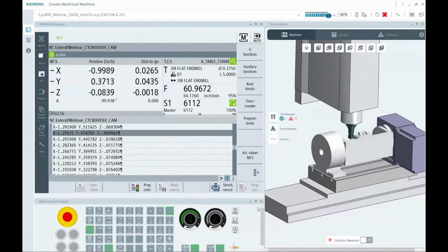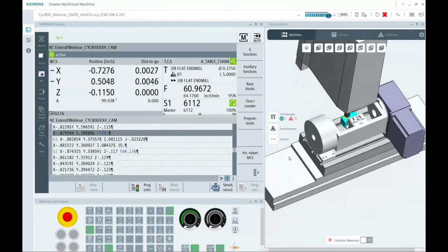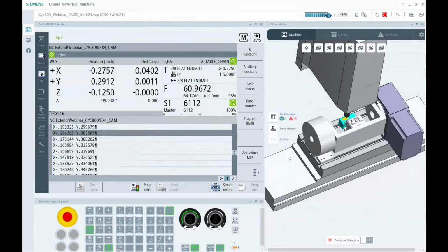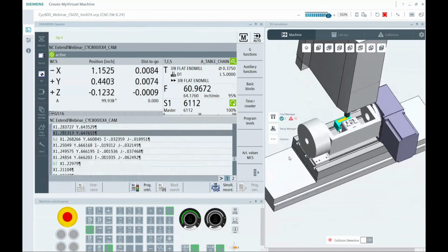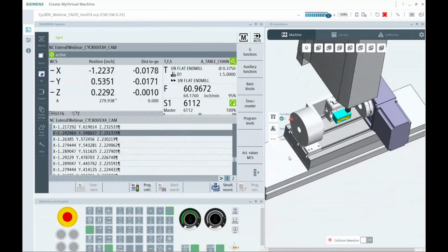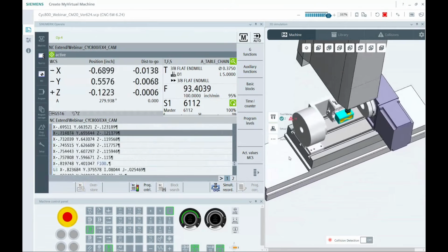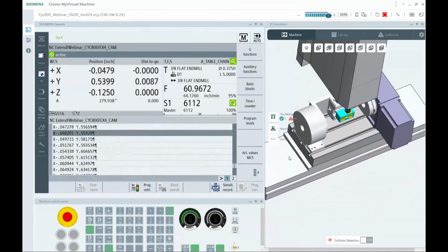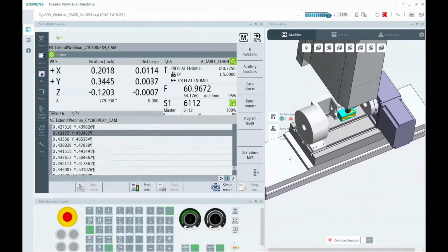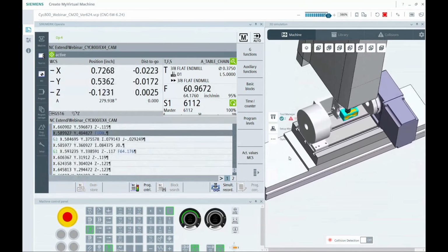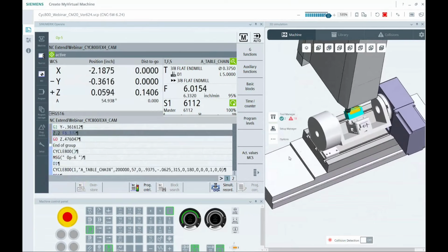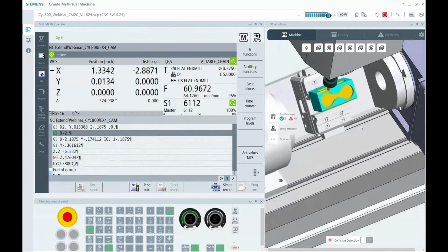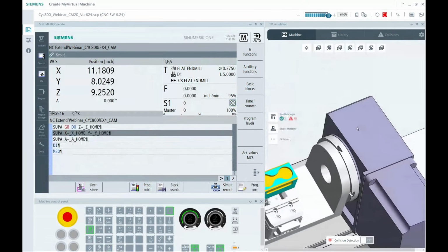There we have our first pocket on that back side, a little dynamic milling to machine that little pocket. And then we're going to wrap it up. I see some CAM systems will use a retract strategy in Cycle 800. Some will still do it with a SUPA on their own. It's not bad either way. Really up to the post developer if he's got his head around it. There's a little chamfer action. There's a little chamfer on the back side. All right, so there's our part.